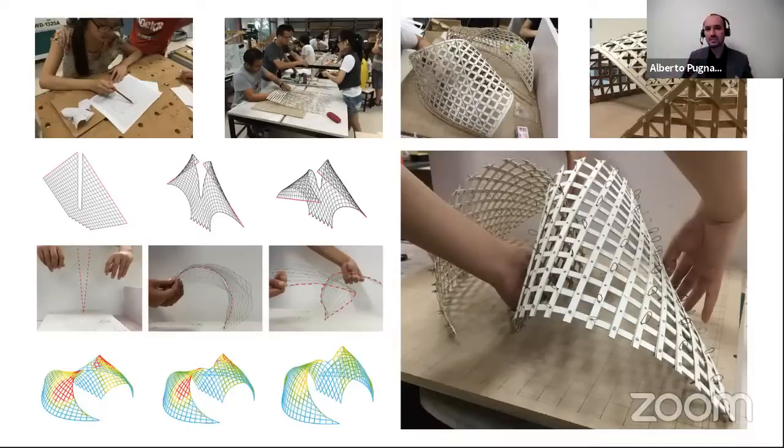And in the first week, I start with active bending gridshell. So we use a variety of analog and numerical tools for form finding, and the focus is on generating architectural space and at the same time being careful about detailing, therefore resolving the connections to the ground, for instance, and the bracing system, which are all, in my opinion, essential aspects of what is the final expression of the structure. We use scale models, which are not as accurate as full-scale prototypes, but they're good enough to develop that awareness of real-world issues, which are generally impossible to grasp by only working within the digital domain.